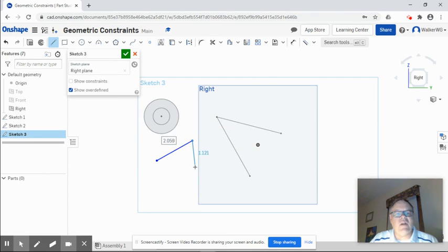I'm going to draw a line this way. You have to hit escape to do another line. Click on line again, and this time I'm going to make this one kind of come down this way. Escape. Again, distance and length don't matter at this point. We're not doing dimensional constraints. Okay. So if I want to make these parallel, I click on the parallel constraint. I click on, let's do this line first, this line and this line, and you notice this line then turns to go in the same direction as this one, making those lines parallel. So and then green check mark.